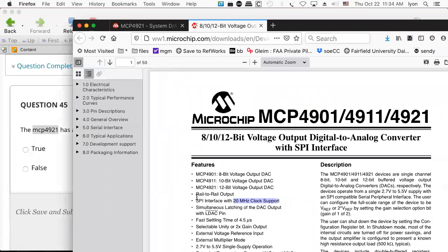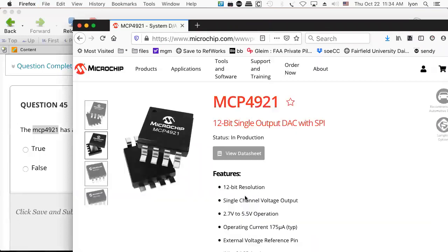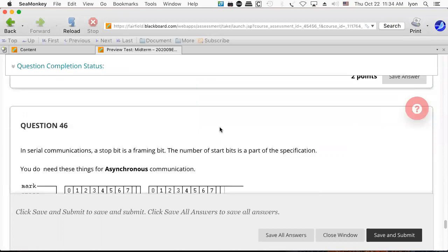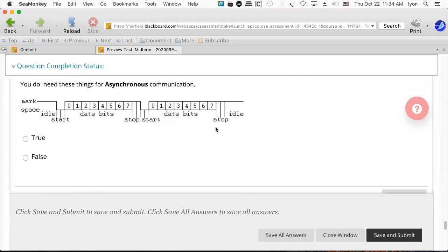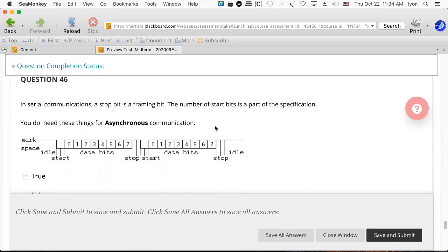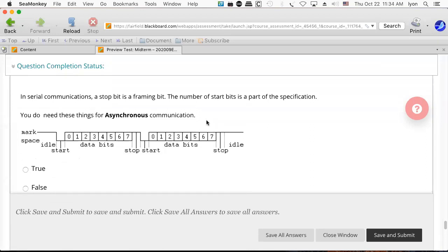But that doesn't mean the chip couldn't take it. At least this chip can take it. And that's the thing about SPI, right? I mean, it can give you a serial clock and you can distribute it across many chips, but you can't go any faster than the slowest chip. So if you've got a chip that won't take 20 megahertz, then you're out of luck. You could probably just throttle the data rate down, something a little bit more reasonable.